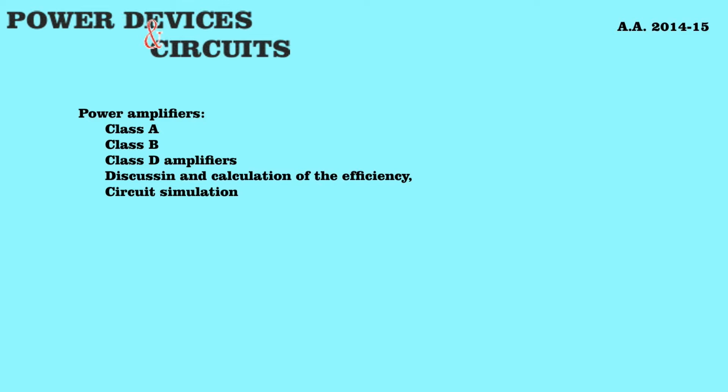Now, let's focus on the power dissipated on the device. We can write down an equation for the power balance in the circuit and say that the power from the power supply is equal to the power dissipated on the device plus the power dissipated on the load plus the power on the polarization circuit, and this is the negative supply circuit.